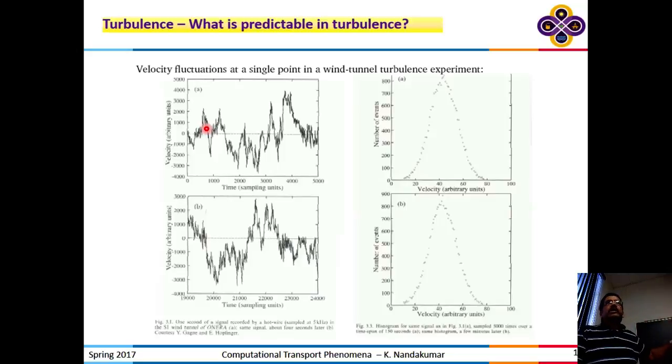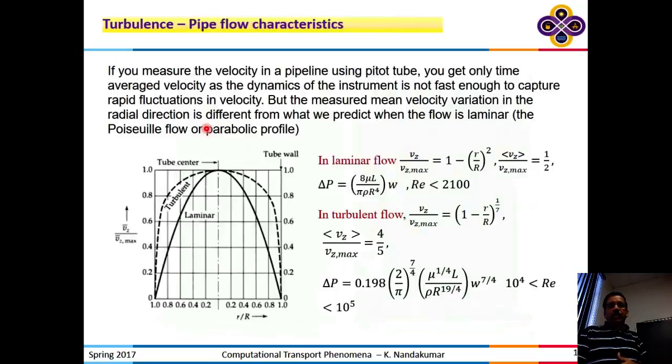But there are tools available, both computationally and experimentally, to construct these distribution functions or histograms, etc., to characterize what turbulent flow looks like, in the homogeneous regime away from the walls and in the regime near the walls. So we have an understanding of how turbulence changes from the wall to the core. This is actually capturing that kind of data.